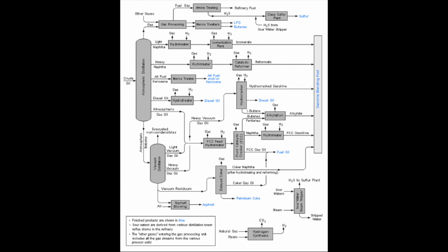So all of these like hydrotreaters and catalytic reformers and alkylation units are all different kinds of reactors carrying out different chemical reactions. In this case, the jumble of hydrocarbons, or compounds containing hydrogen and carbon, that come out of the ground as crude oil are broken down, hydrogenated, heated and cooled, and reacted with other reactants to form things like asphalt, fuel oil, gasoline, sulfur, etc. You can see how chemical engineers have to deal with plenty of reactions, materials both in liquid and gas phases, and transfer different materials to different unit ops.